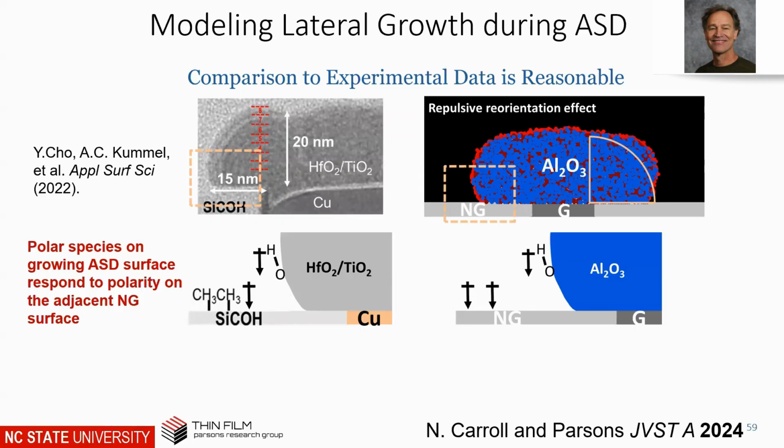Yeah, my same question for her was, if you really want to have the lack of mushrooming, are you going to need one of these double area selective processes, where your passivation layer was a selective deposition process that somehow just magically didn't mushroom?